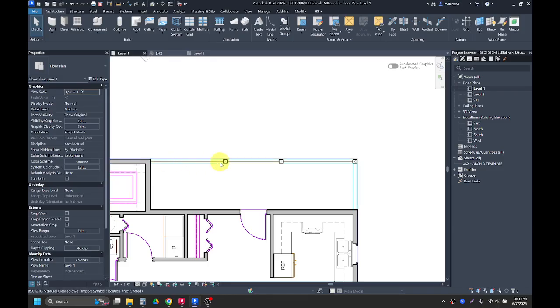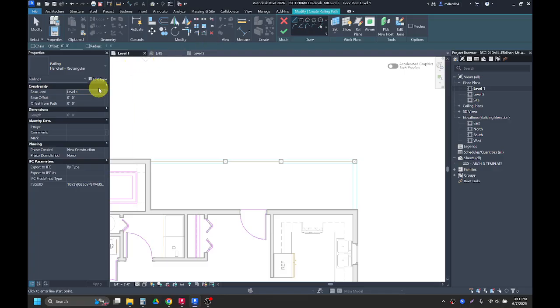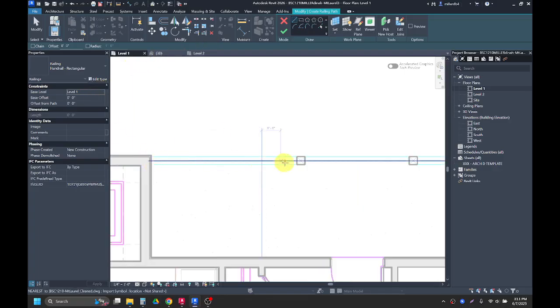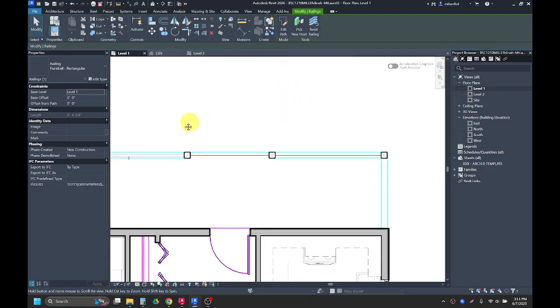We're going to put railing here, here, and here as well. So the railing, because of the fact that we have to do them with breaks in between, we have to do it as 3 separate railings. So in the architecture tab, we're going to click on railing. And then I'm going to just draw based off of the middle of my column over and hit my green check.